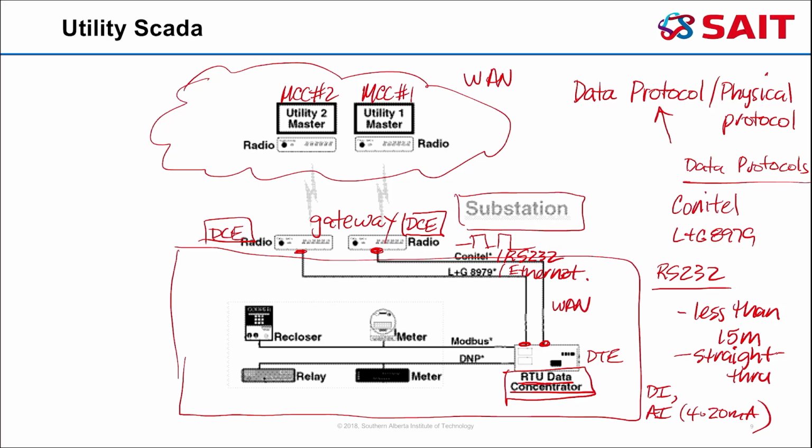So as an example, if we've got a protection relay that's monitoring line current, why would I connect a 4 to 20 to monitor that line current as a field loop to the RTU, when I can simply, through communications, ask that smart relay for that value that it's picking up by a CT or a PT, and report that value back to the MCC as a value that was collected by data communications, as opposed to reading it as a field loop.